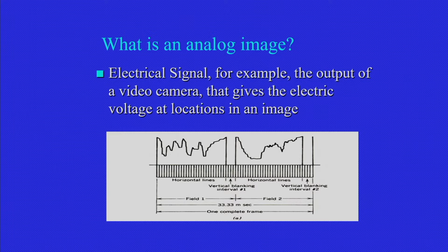In TV standards, I know some of the standards like PAL, the phase alternating line. This is one TV standard. Another standard is NTSC, and another standard is SECAM. I am not going to discuss this, but in India we use the PAL system. In the PAL system we have 625 lines, and we have considered 25 frames per second. This is a TV standard, 625 lines and 25 frames per second. In NTSC generally we use 30 frames per second.